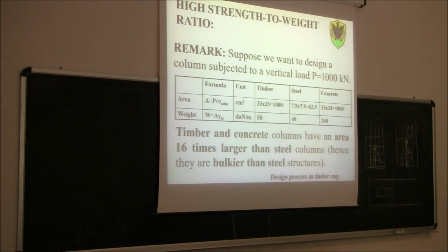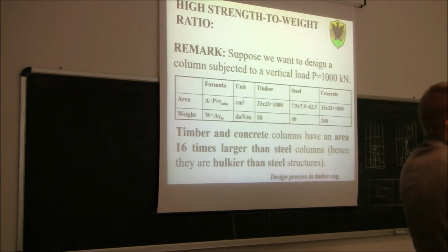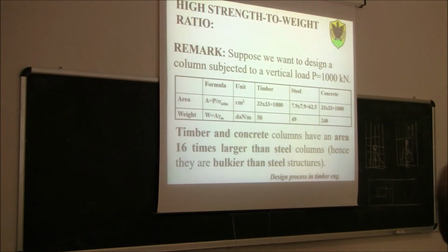So if your client wants to do an almost invisible structure, you need to tell them, look, you can't use timber, you can't use reinforced concrete. The only thing you can use is metals, aluminium or steel. Or if you want to use concrete, you use high performance concrete, concrete with a strength which is 10 times the strength of normal concrete, and you can reduce the thickness. Okay? It's clear.